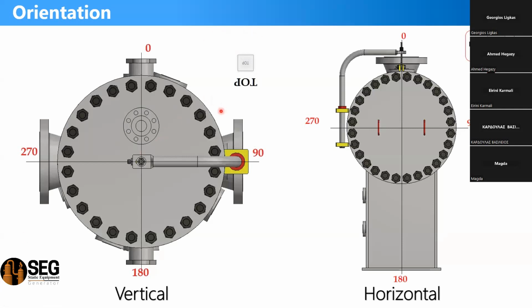to get the correct orientation, you should take a look from the top view, and as you can see, the top text is flipped to be the front to be here. So 0 degree will be at the front view, and that means the 90 degree will be on the left view, and the 180 will be on the back view. So that's the top view. Let's take a print screen here